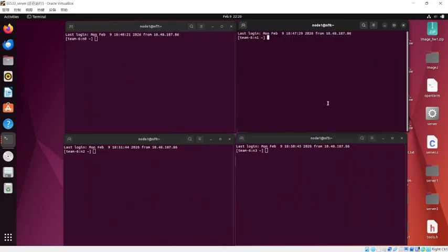So all the modifications are made, and the next step is to make the bit file and implement it on the NetFPGA board. So we use the make command, then SCP it onto the board, and use nf_download to implement the bit file. I've already SCP'd the bit file onto the NetFPGA board.